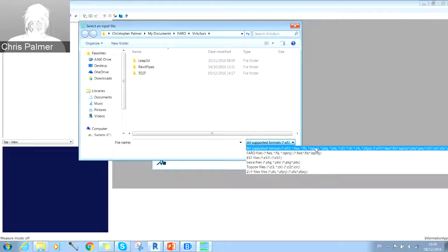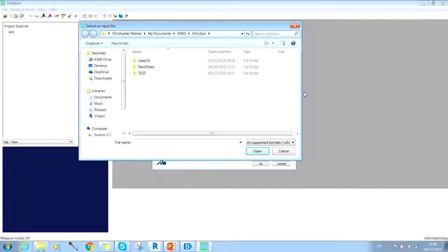A lot anyway. We've got particularly E57. Obviously we prefer to use an ordered FLS, that would be the best solution for us, but we can also take E57s. We've also got some other formats in there, PTG, PTX, so we've got a lot of different files we can support currently. That does need to have the same coordinates as your RCS files or your RCP project in order to make the link work correctly. So really don't update your origin in ReCap if you're going to be using this link. Is this the answer? Okay, thanks, Chris.